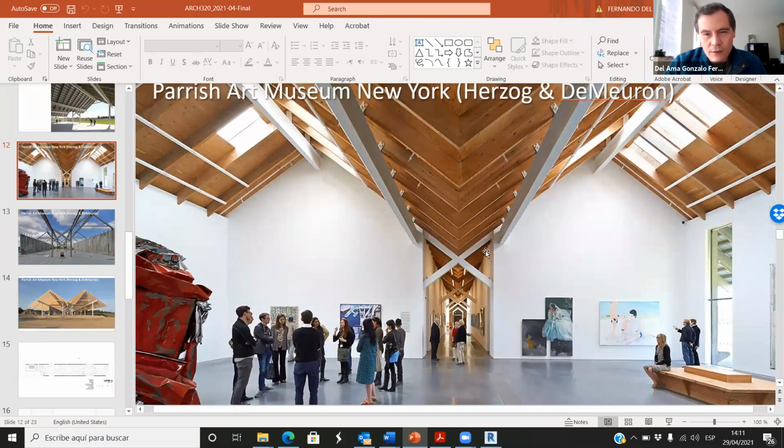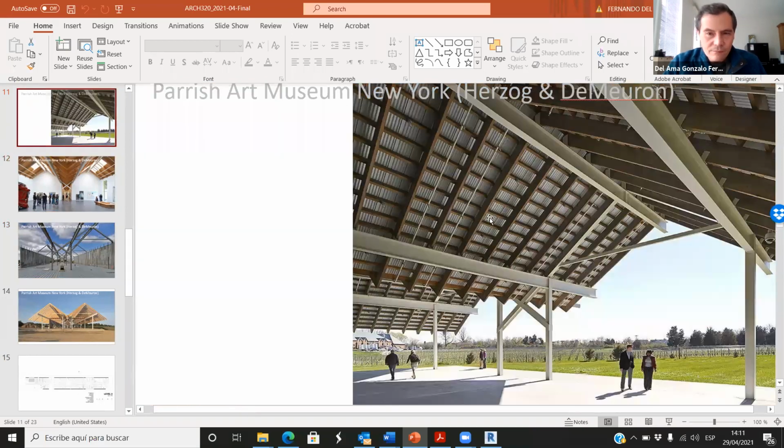A lot. You see that here we have this element, there's another element there, and we have a lot of them. This is not a truss. Those are just beams. So you can copy this element without this cross here, and by repeating this element, it makes it look better. Probably with this truss here and another there would be enough from the structural point of view, but by having more, things look better.